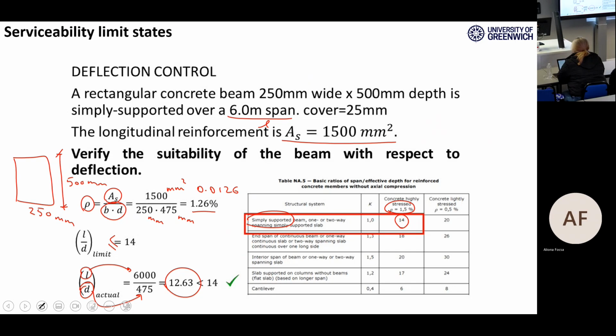What you can do is increase the dimension of your beam, especially the height of your beam, right? And that causes some additional problems, obviously, because you cannot increase the height of the beam significantly because it will go down and you will see it. You have a problem with the finishing. It depends on the case, but you should change something to comply with this criteria.